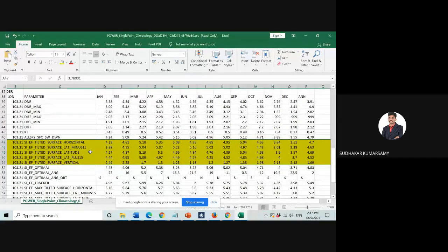for different locations, as we discussed for an ASEAN location when we started with the PV system, PVWatts, we were doing some exercise in the beginning. So at that time, we chose one location; whatever location you have chosen, use that also. At the same time, also do the analysis for your home location, your house, wherever you are staying. For that location, find what the solar radiation available is, and then plot the solar radiation profile for the given location. So this is a small laboratory exercise report which you can make.